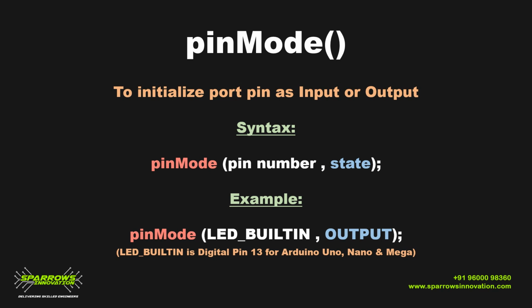This pinMode is a single time initialization command. That means if you initialize this command in the beginning of your program, for the entire program, pin number 13 will act as an output. That is, your LED_BUILTIN pin will act as an output. So we have to use this inside void setup. We need not use it inside void loop because we need to initialize only once. So use it in the void setup.